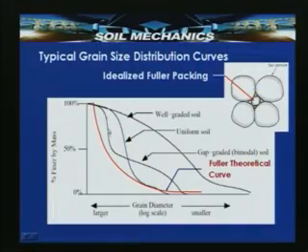It will be uniformly graded to some extent, and then there will be an absence of certain particles. This type of curve is called gap graded or bimodal soil. So, the soil can be well graded, or it can be uniformly graded. This is an example of desert soils, where the soil grain particles are uniform in nature.